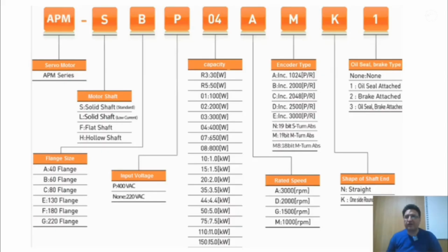Let me point out that the difference between motors with brakes and those without is that motors without brakes have a shaft that is normally free. But motors that have brakes, their shaft is normally locked. So, in situations where the power to our motor might be cut, if our motor has a brake, the shaft is locked and doesn't move at all, which can really help us in terms of safety.